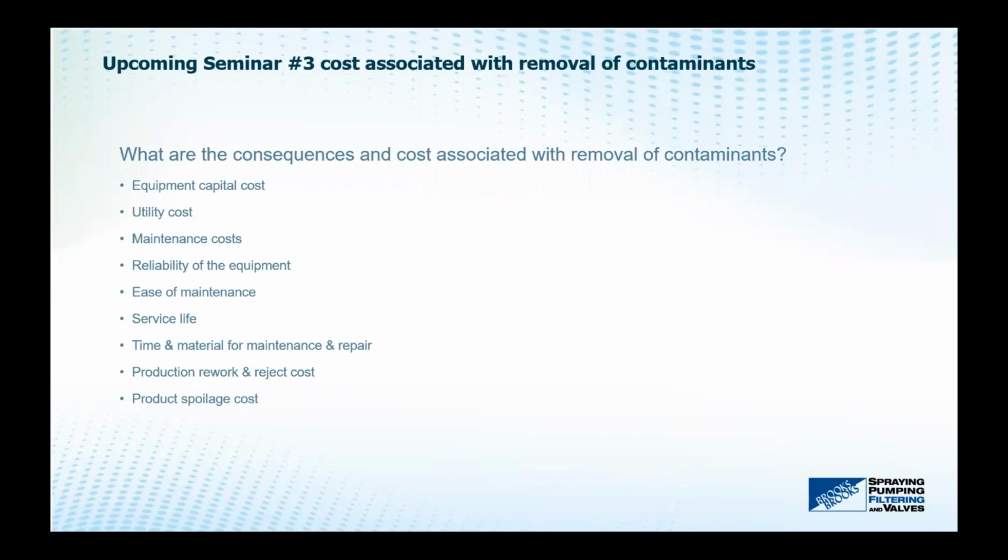As I initially stated, air is free, but once you compress it and purify it, it does have an operating cost. You need the electrical heaters to regenerate the desiccant, or you need the motor for the refrigerant dryers. So there's always costs associated with each design of dryer. And we're going to elaborate a bit more on that aspect, the operating costs of purifying air. So the most cost effective, I'm getting ahead of myself, so I'll save that for next time.